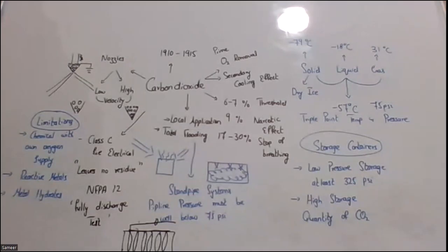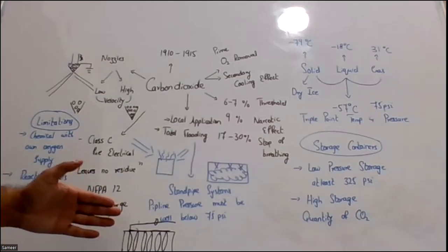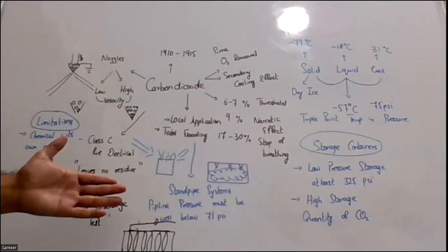Sometimes we have too many toxic vapors in an environment. For that purpose, we may schedule the maintenance much earlier also. But we can have devices that can be tested, checked, and replaced. And during the maintenance, sometimes you may require only a couple of extinguishers, or a partial discharge may be required, to see the operating principle of the carbon dioxide, and whether there is any type of leakage in the piping, because of the toxic vapors.